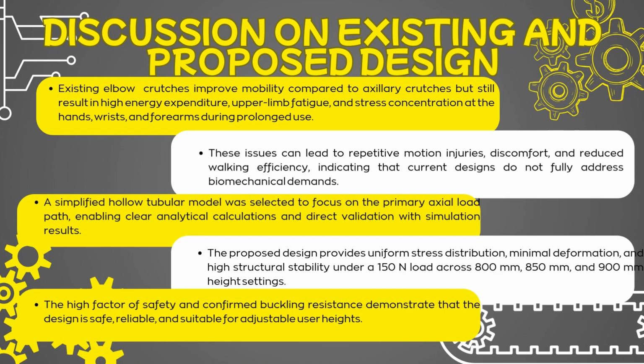Under a 150 newton load, this crutch shows minimal deformation and very low stress for all three heights. Finally, the high factor of safety and buckling analysis confirmed that the design is structurally safe, stable, and suitable for adjustable use without compromising user safety.